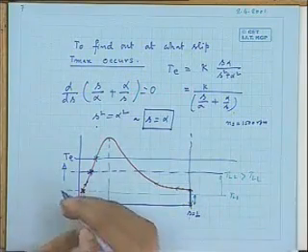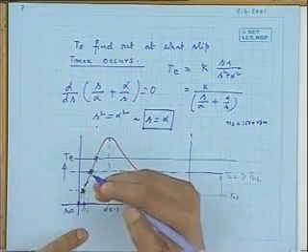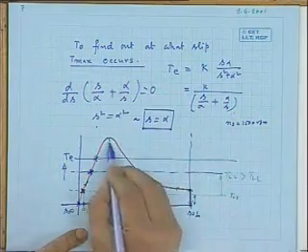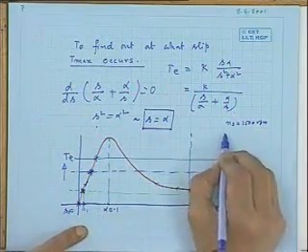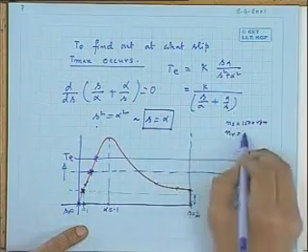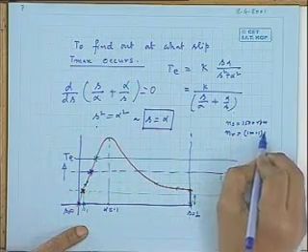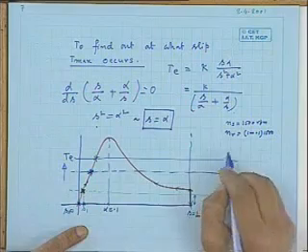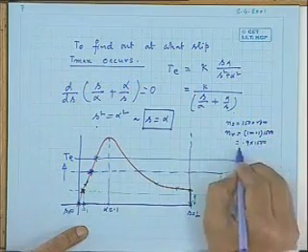That is the absolute no-load condition. The machine will run here. I am gradually increasing the load torque on the shaft of the machine. Then in this zone, what will be the speed at this point? That is 1 minus S into 1500 RPM.